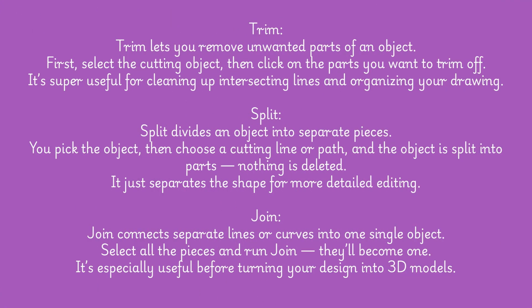Trim. Trim lets you remove unwanted parts of an object. First, select the cutting object, then click on the parts you want to trim off. It's super useful for cleaning up intersecting lines and organizing your drawing.